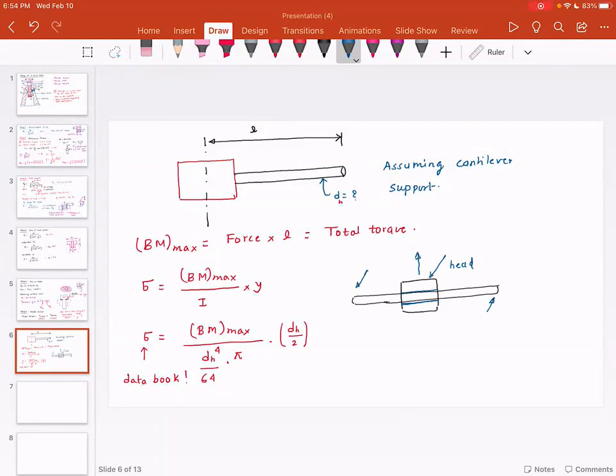In certain cases, you will notice that the torque requirements are super high. So in that case, what I have seen happening is you actually attach this to a transmission. So you have the head, and this head is somehow attached to a transmission, either using some sort of drive, gears, some sort of power transmission system, and then you could have a gear assembly, and then you can have a motor that rotates this system.